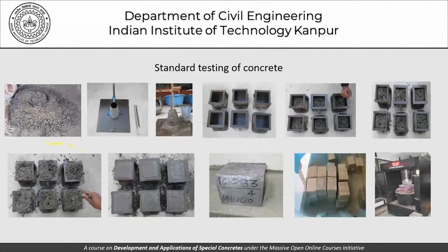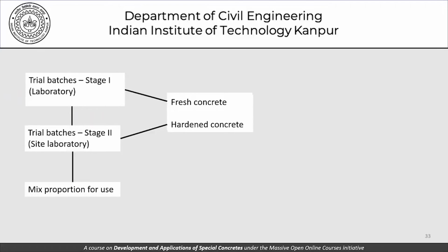Now, once again, I'm drawing your attention to the regular standard testing of concrete, the way it is shown here. This is where we stop. We proportion the concrete through the laboratory tests, come to the site lab and finalize a proportion.